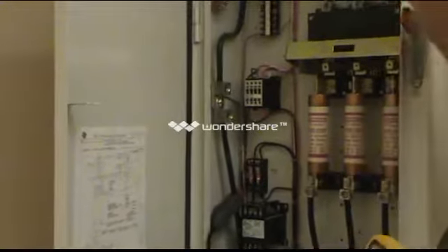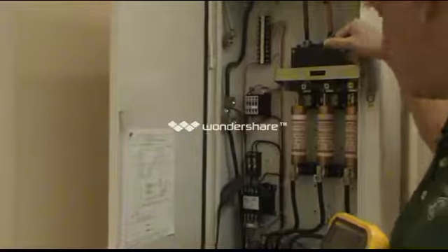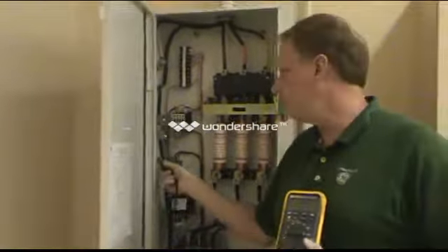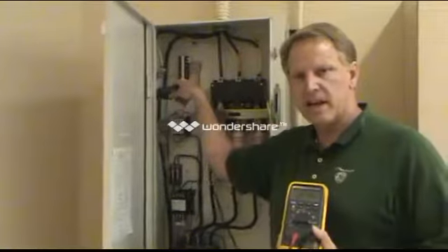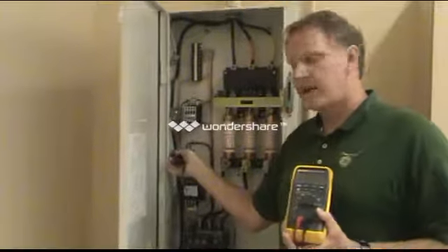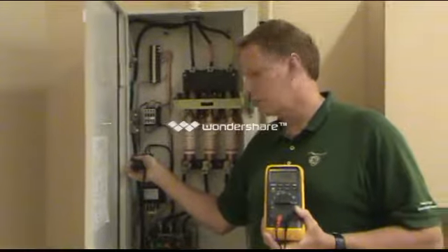Now, system power off to the equipment, I would flip the breaker and I would retake those same readings. So facility side with power off and the breaker tripped. Load side, power off, breaker tripped.